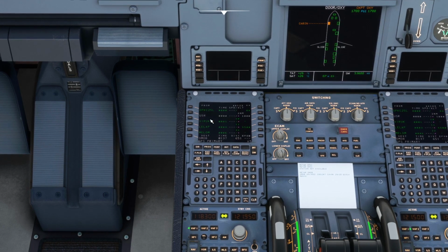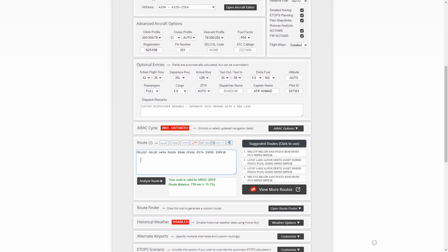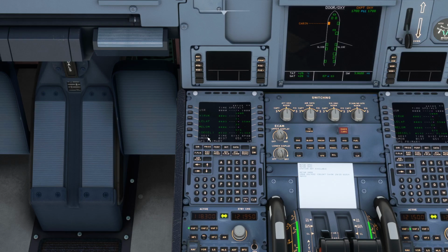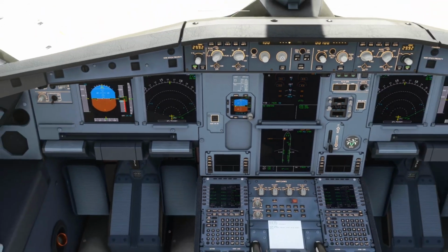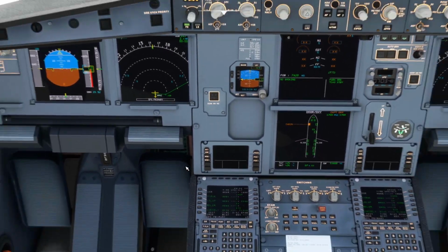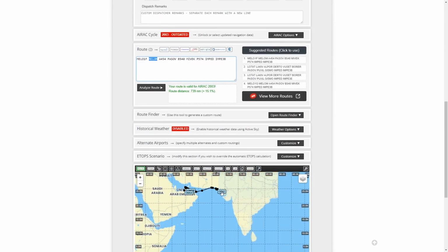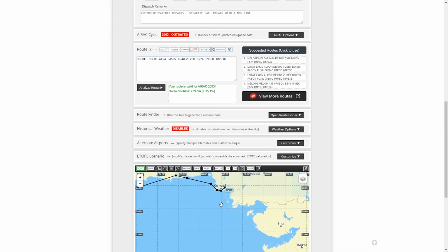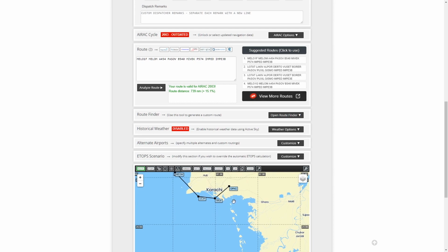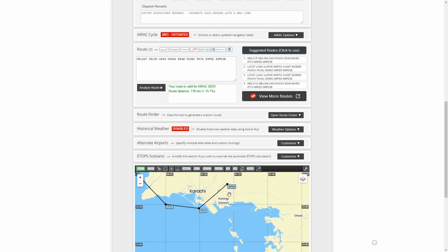Now you can see this thing that there is a departure procedure that's been set into the MCDU. That's OPKC 25 left, and then all the waypoints which you will be taking, and you will go to Melem. As you can see, Melo 1F will take you to Melem. Okay, so Melo 1F has taken you to Melem by following all these waypoints, video, Claylab, and that's it. If you want to see your flight plan visually, you can see it over here in SimBrief, as I told you before. You can do it over here, and you can even go to your plane's navigation display and see whether it's properly updated or not.